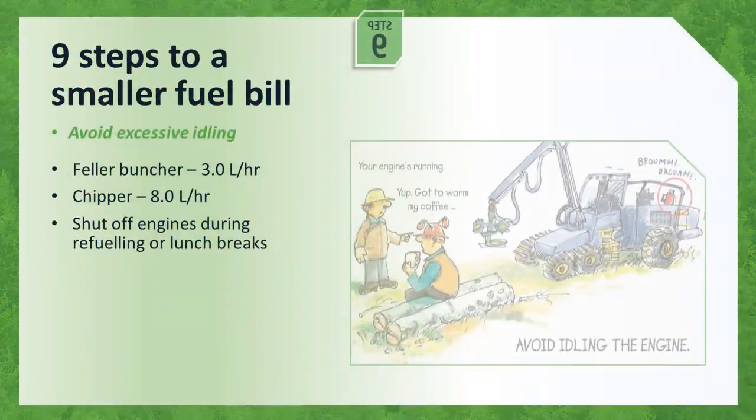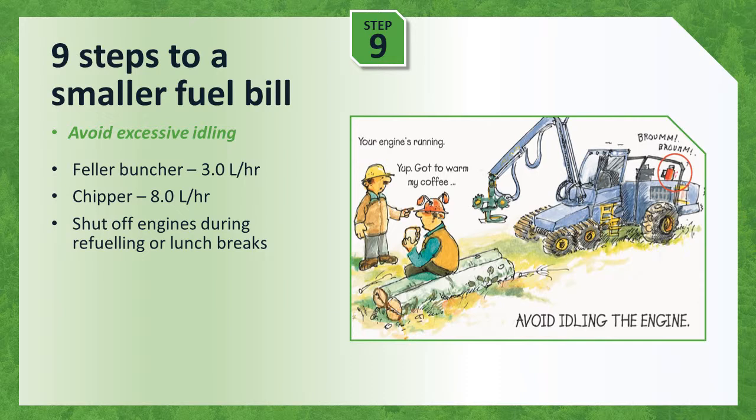Step 9. While idling, your engine consumes a considerable amount of fuel, which can be avoided. The cooling capacity of the engine is optimized for heat rejection when maximum power is required. When excessive idling occurs, which can be considered idling for a half hour or longer, the engine can overcool, causing more wear than when it is working.